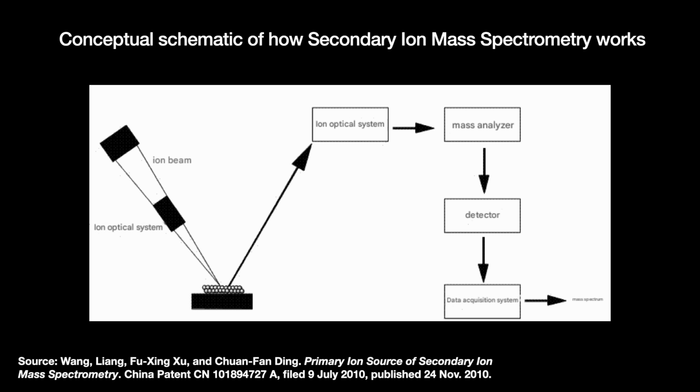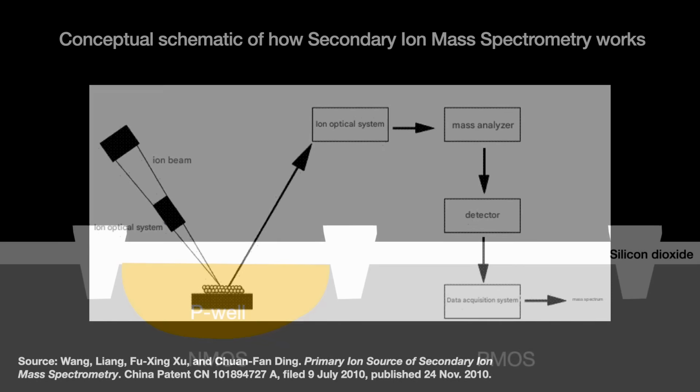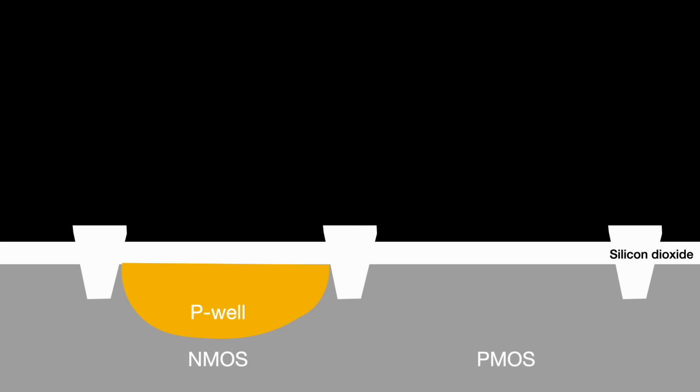The metrology tool is chosen for its high sensitivity, but as its measuring is destructive, use should be limited. If everything passes, then the photoresist is stripped off using the aforementioned oxygen plasma ashing method that I talked about earlier.